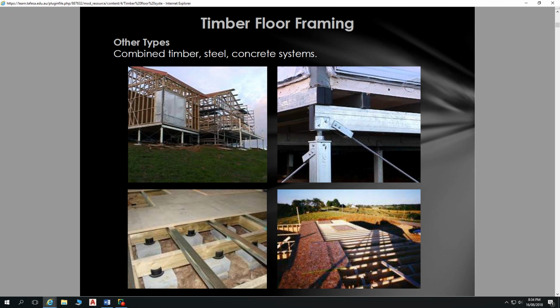So you've got your auger on an excavator, digs a whole bunch of holes, and then you fix your RHSs to that with dynabolts at the base, or RHSs or timber stumps in some circumstances. Fix in your framing, which happens very quickly, and then top your floors either with a product like this, a structure floor, which is made of a composite particle board, or plywood as well.